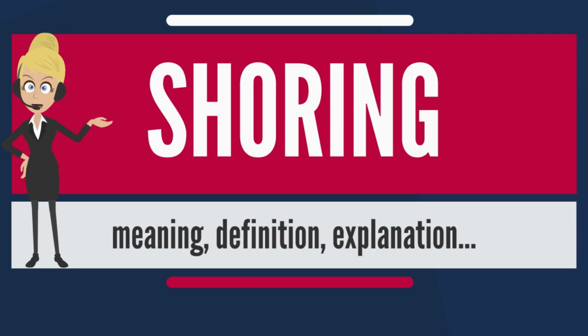Vertical shoring is used to support a hatch or splinter box on the deck, consisting of a vertical timber between the deck and deck head, with two wedges used opposing each other to tighten it. Pad pieces are used to spread the load on weak structures.